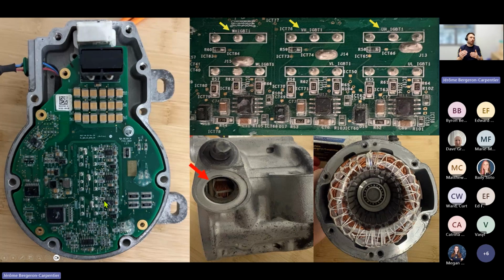So it's going to be an extra superheat. That being said, having extra superheat is going to prevent any liquid from going through that compressor. But because we do have that extra superheat from the heat captured from that inverter, we already have some heat for the compressor to compress. So the compressor would have to work a little bit less, right? So it's all part of the strategy of having a system that is super efficient.